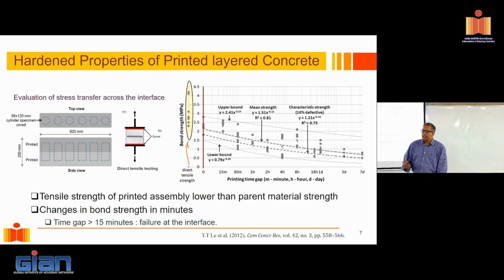Why? Because when we design concrete structures, we take the characteristic strength. What is the characteristic strength? It's a 5 percentile value, right? What does that mean? I'm taking a 5% risk. There's a 5% probability that the concrete that I'm producing is weaker than what I'm prescribing. That is a 5 percentile value, right? Which also presumes that my standard deviation is within some limit. You can't just have random standard deviations, right? And what is the standard deviation we typically take? It's about 5 megapascal. That itself is quite high, right? Which means that you have some semblance of quality.